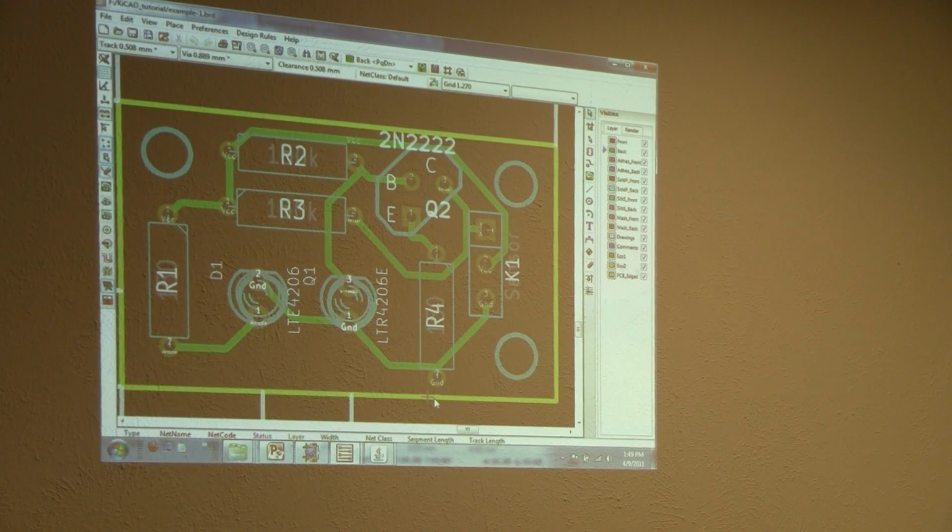Now, you remember in the schematics, we named something VCC and ground. You see this wire is named ground, there's that anode that we named, and there's VCC. Well, what's this one? I don't have a 3-button mouse, so I'm not sure, I think a double click. But if you expand this up higher, you will see that even the wires that you didn't name have a netlist name, something like N463223, which is not very intuitive.